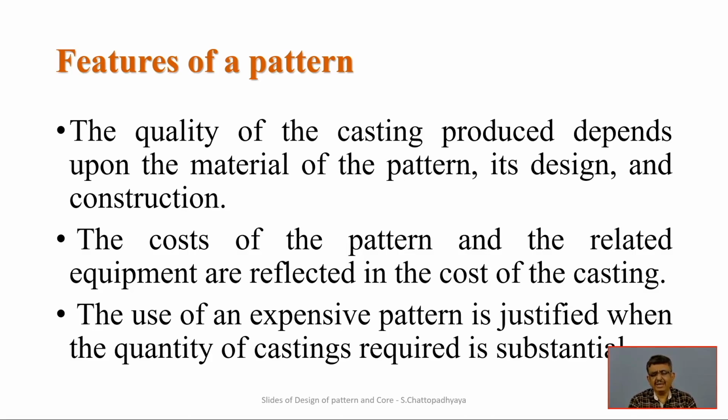Though we can generate very high quality castings with investment casting, the cost of pattern making will shoot up, because every time we have to make the pattern. This is why these processes are called sacrificial pattern based casting. The use of an expensive pattern is justified when the quantity of castings required is substantial.